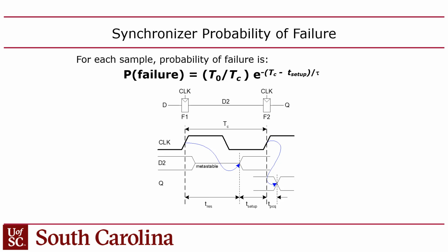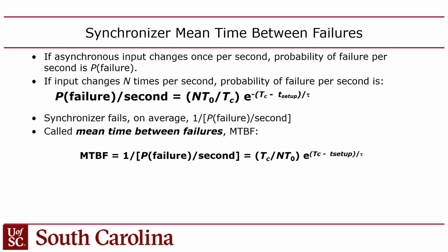Okay, so once you have that, then if you know how many transitions you get per second, like for the FPGA, if you take the switch and flip it, like on your lab 3, you keep flipping it as fast as you can, right? Then you can calculate the number of times you flip that switch per second, and that will become n. N is the number of times you flip the switch per second. And you multiply that by the equation, right?